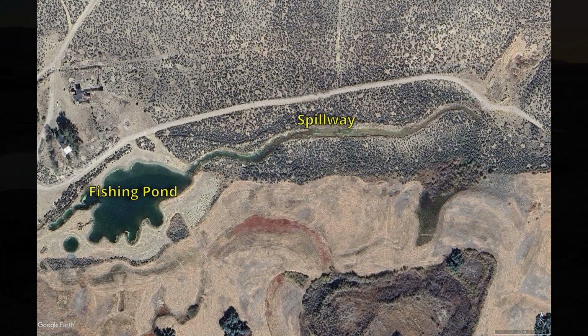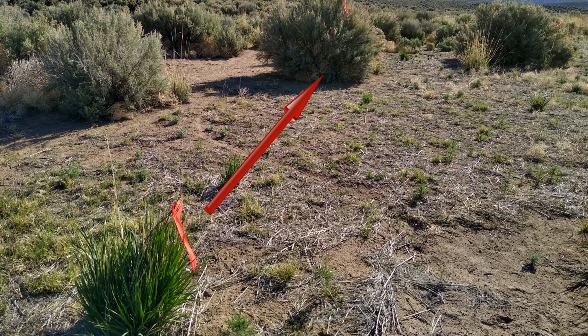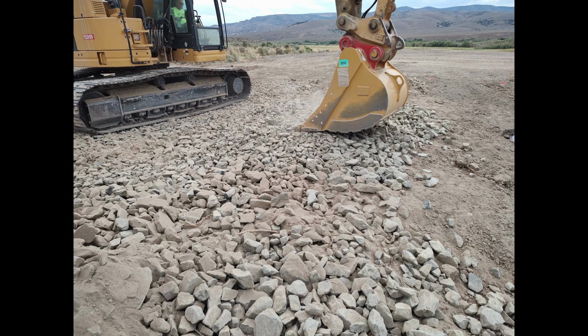wet meadow wetland. One of the first steps in building the spillway was to decide where the spillway would begin and where the spillway would end. We selected undisturbed ground at one end of the dam that was built for the fishing pond to be where water would enter the spillway. We purchased rock for armoring the entrance of the spillway. The rock armoring at the entrance of the spillway was needed to protect the area from being rutted by motor vehicles that were driving around the fishing pond.